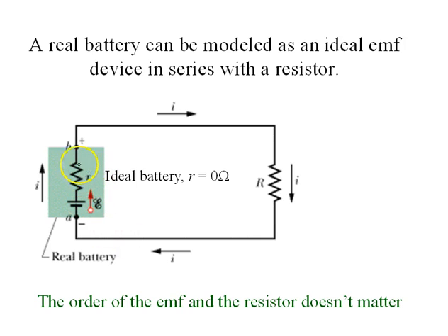If we're just trying to solve for current, then it doesn't matter where any of the series elements are, we can move the elements around. And that's what we're doing with these circuits, we're mathematically modeling. So just like when we are adding, we can move the variables around in our circuit, and that doesn't change